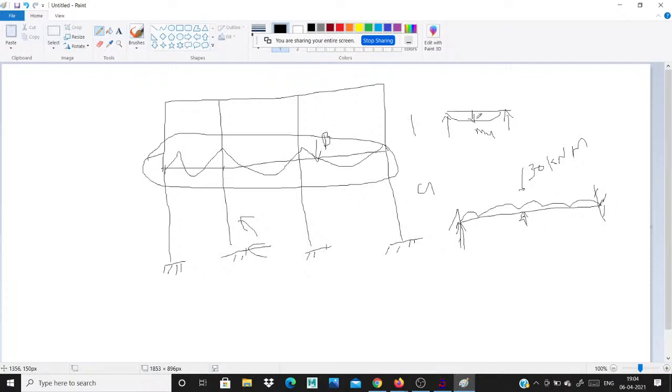See this, the beam depth will be higher and the column depth will be less. For a simply supported beam, the beam depth is smaller and the column depth is a little higher. What is the difference? In a simply supported beam, the moment does not carry over to the column, and the corner is 0. But in a continuous fixed support, some of the moment is carried over to the column. So for column design you take the moment also. That is called a fixed and continuous beam.